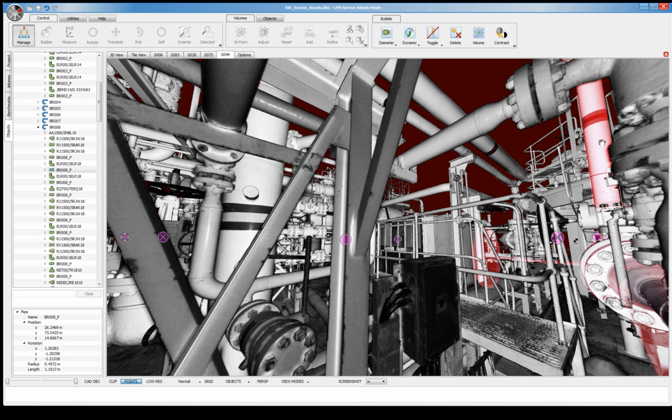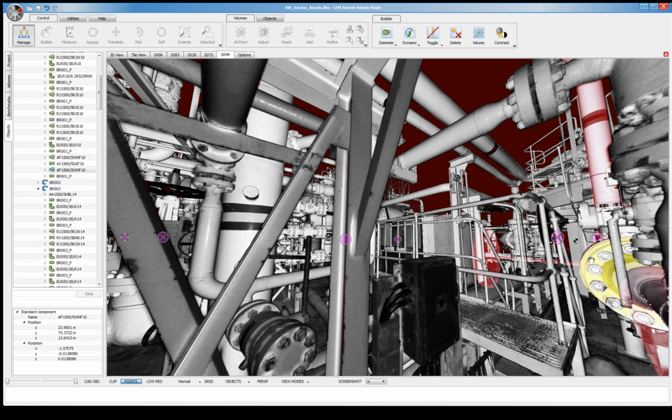what you can do is to go back up to the option, and then we've got a new mode called Dynamic Objects. So if I put it into there, it should go back to being a standard bubble view until I move the cursor over something that there is a model behind.